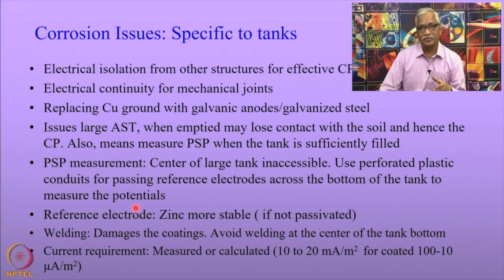The other issue that is specific to tanks is during the commissioning of the tank, and one should avoid welding at the center of the bottom of the tank, but that is easier said than done. When you are welding, the coating gets damaged, and then the current requirement to protect the tank at that location becomes very high.